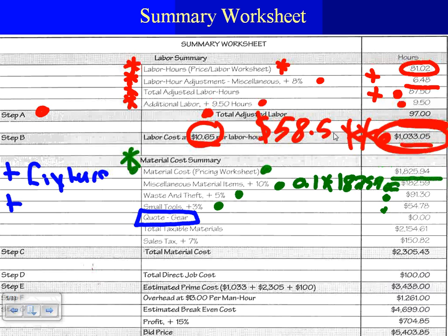You send all the schedule, all your panels, the amp, the voltage of every panel, the gear inside the panel, the receptacle, circuit breakers in your panel, so they can build them for you, as well as transformer size and all this stuff. You send them in a gear code. All these mechanical, you send them to Cutler-Hammer, Square D, Siemens, and those guys will come up with a detailed code for you.